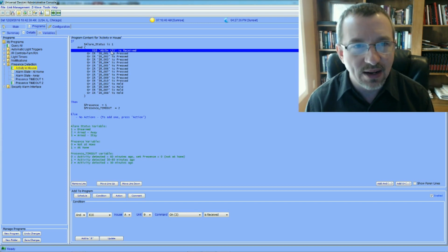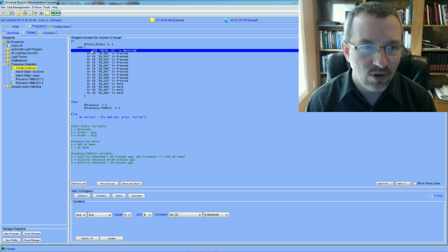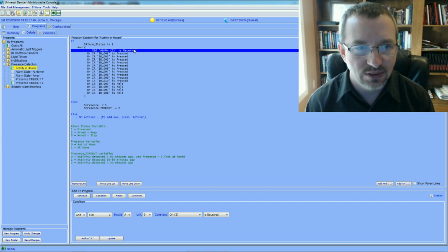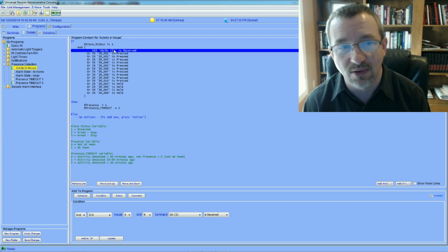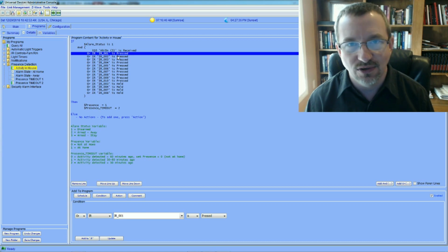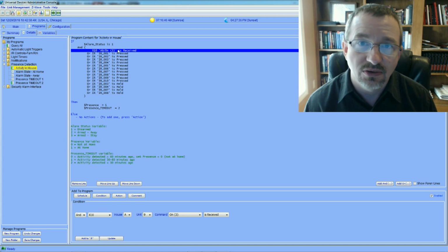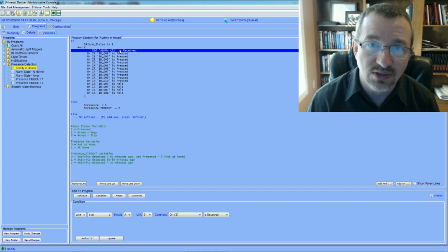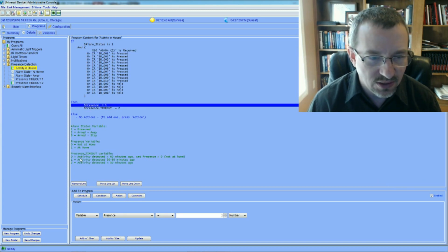So if you're moving around in the house, you're going to be setting off motion detectors constantly. That one X10 command is really an aggregate of 30-something zones on the Honeywell alarm system that it's monitoring and saying, hey, somebody's moving around, somebody's opening the door. And then all these are infrared commands because that means somebody's using the remote that's in the family room. This is the more common one, though, to receive that command from the alarm system saying that there's movement. Then you set presence equal 1, and that presence equal 1 means we're at home.